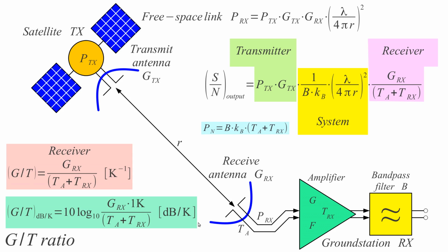These lobes are collecting ground temperature, because the ground is at 290 kelvins compared to the 10 kelvins of free space. So if we were able to reduce the side lobes of this antenna, we could decrease the antenna temperature much. With satellite reception, it makes sense to invest in having the lowest antenna temperature, even if we compromise the gain a little bit.